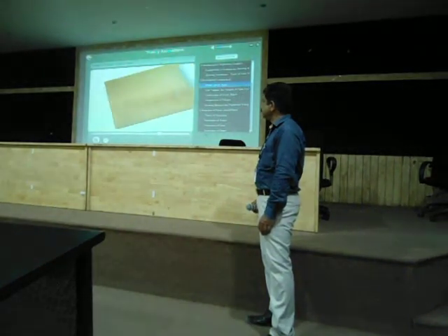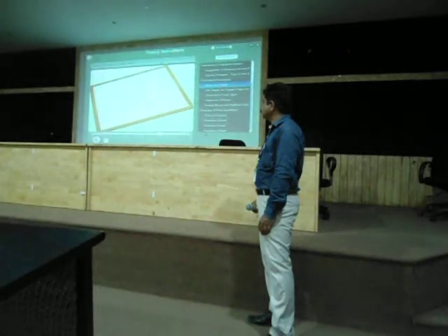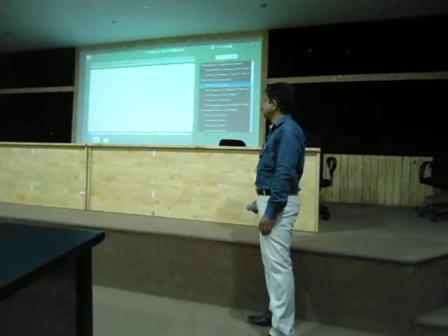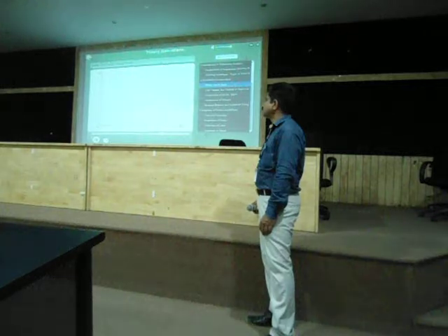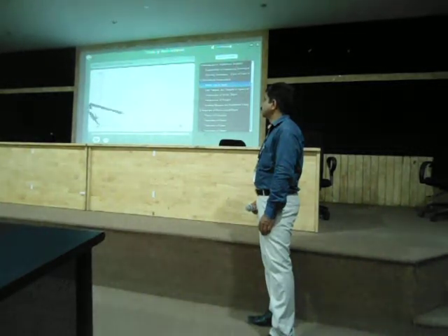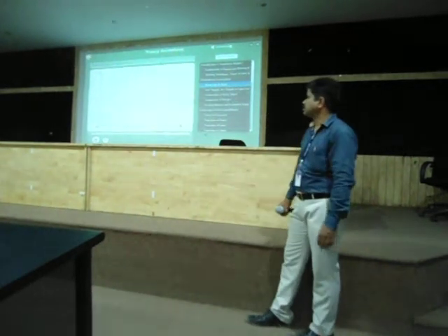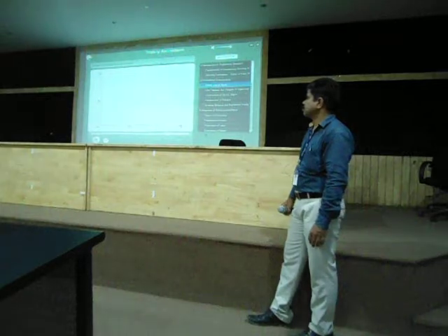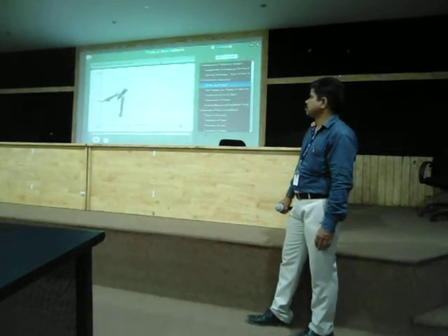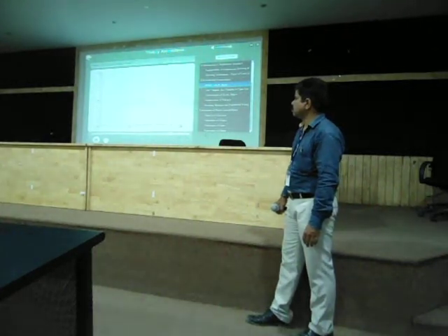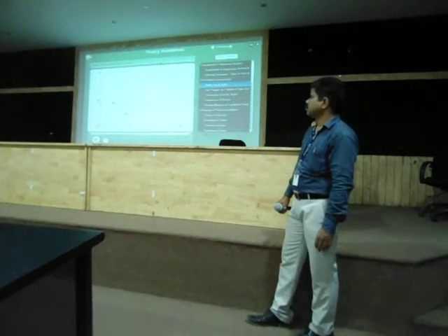Now let's crack something tough. For that, we will divide a right angle CAB into 3 equal parts. Let's take A as center and with an arbitrary radius R, draw an arc to cut the sides AC and AB at points P and Q respectively. Then, with P and Q as centers, draw arcs to cut the arc PQ at M and N respectively.